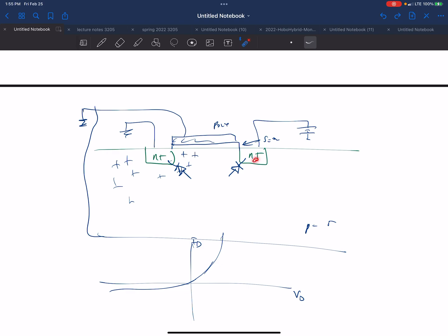And this diode has a higher voltage on the N plus than on the P, which means it's kind of here. It also has no current. I'm hoping you guys have seen this diode. This is a really tiny current. This reverse bias current is tiny, like 10 to the minus 16 amps or something. So basically, you've got two diodes that are off.